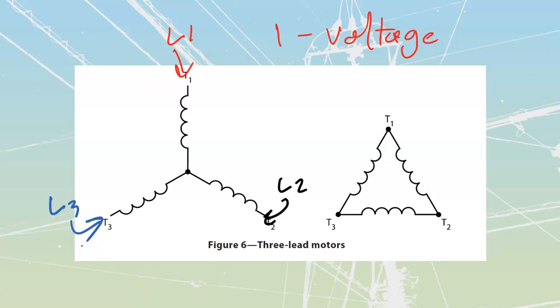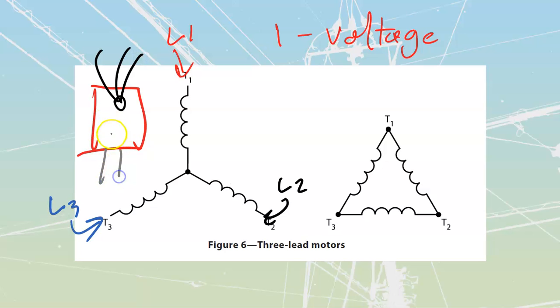When you are doing motor connections, by the way, for those of you that have never done motor connections before, these, if they are a wire lead inside of the motor terminal box, just kind of draw a motor terminal box over here. I'm going to have the leads come through a rubber gasket from the motor itself. Carry those 3 leads out like that. Then I'm going to take my conductors in from, we'll just pretend it's a conduit over here, and we've got our conductors that are going to come in like that.